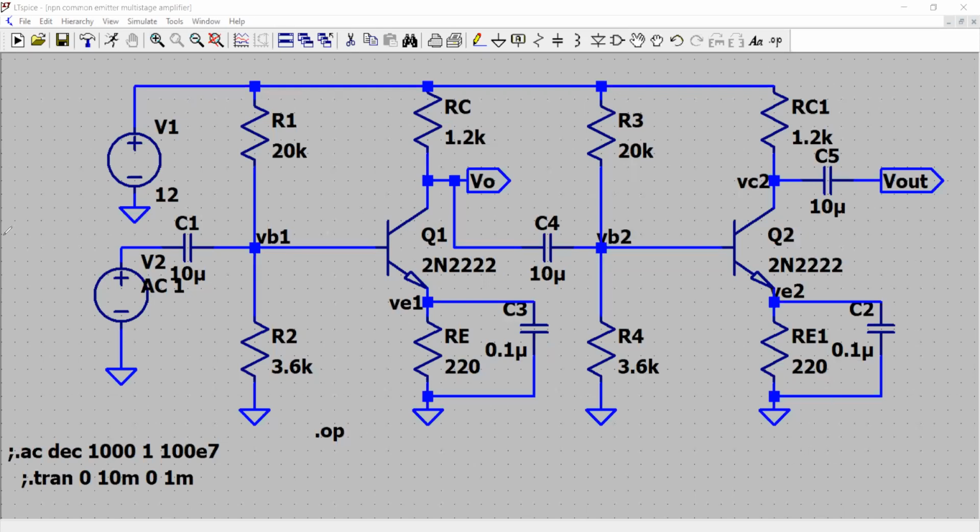So what we see is that the combined gain here will be the gain of 5 from the first stage multiplied by the gain of 5 from the second stage. So we should have 25 as the total gain, 5 times 5. It means the final output would be 25 times the input that we apply to the circuit, which is an AC coupled emitter, using common emitter stages. Okay, and this is a multi-stage or cascade amplifier.